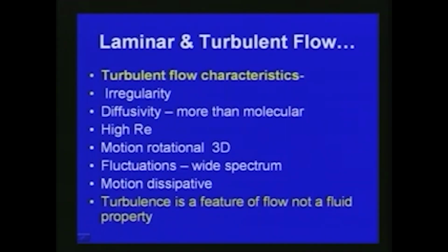So most of the laminar flow, the rotational effect will be very minimal, or it can even be irrotational in nature. But in turbulent flow, the motion will be rotational, and due to this, most of the time we have to consider the fluid flow in 3 dimensions, since with one or 2 dimensions it is very difficult to see what is realistically happening, how the disturbance takes place, and in which direction. So as far as turbulent flow is concerned, we have to do 3-dimensional analysis.